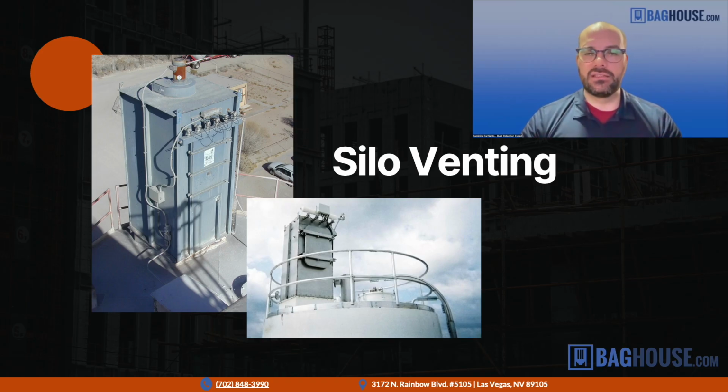Now, moving to the last kind of collector we'll discuss, which is when we have just a silo to vent or an enclosed space, we often use what are called bin vent dust collectors. So here you see a picture of one. Bin vent dust collectors are basically just baghouses that have the bottom section cut off, have the hopper section removed. So that's why they look like two-thirds of a baghouse. Everything else is exactly the same. They have the same filters, the same cleaning mechanism, the same controllers.